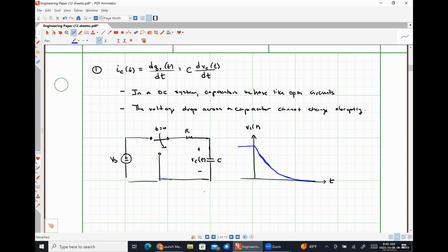So you're shorting a capacitor to de-energize it. It still takes time to de-energize it because there's no way to put a wire that contains zero resistance. Shorting a capacitor to de-energize it is something that's done in a whole lot of troubleshooting, particularly of power electronics, because you do not want to leave those capacitors energized. They literally have enough energy to kill you. You use a special tool, like a screwdriver with a ground wire.